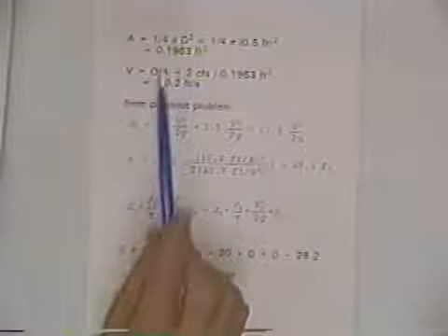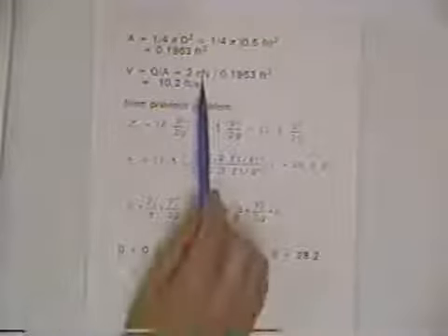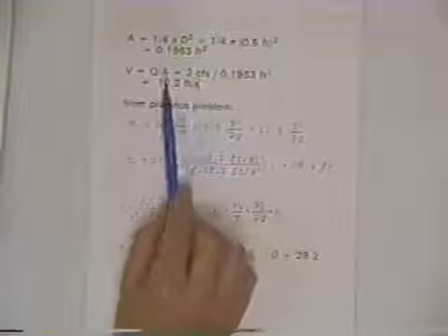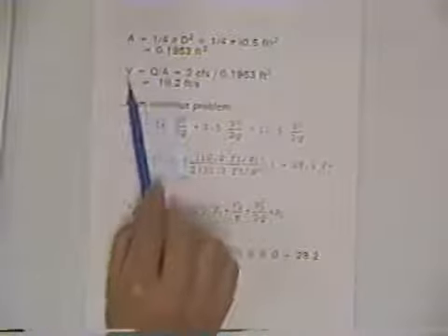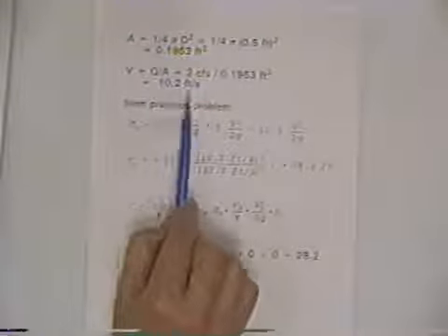So that gives us a chance to expand our energy equation to include that pump head term in the energy equation. A lot of the problem is the same as before. We've got the area, same area as before. This time the discharge rate is given, and since the discharge rate is given, we can divide that by the area of the pipe, velocity Q divided by A, to get the mean flow velocity in the pipe.